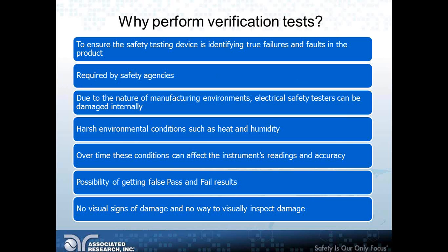Harsh environmental conditions such as heat and humidity can contribute towards electrical safety tester damage over time, and these conditions can affect the instrument's readings and accuracy, making it possible to get false pass and fail results.